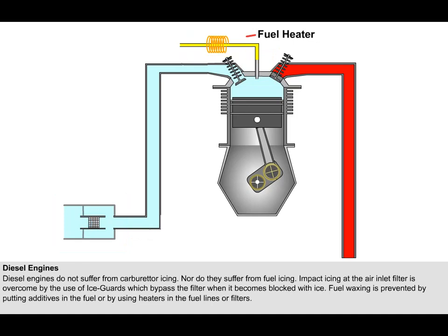The problem of fuel solidification, known as waxing, where the fuel viscosity increases due to low temperatures, is overcome by putting additives in the fuel, or by using heaters in the fuel lines or filters to preheat the fuel.